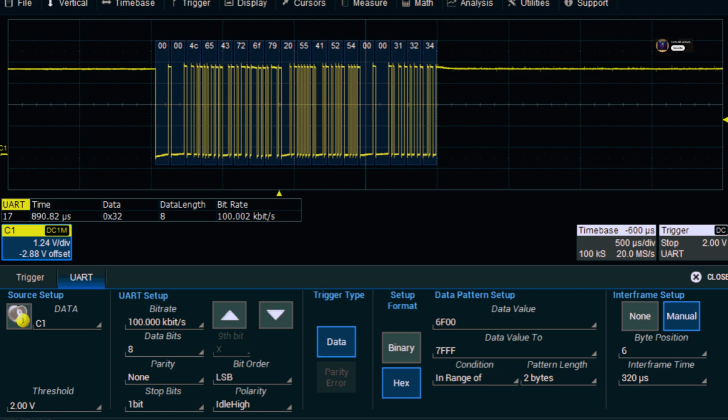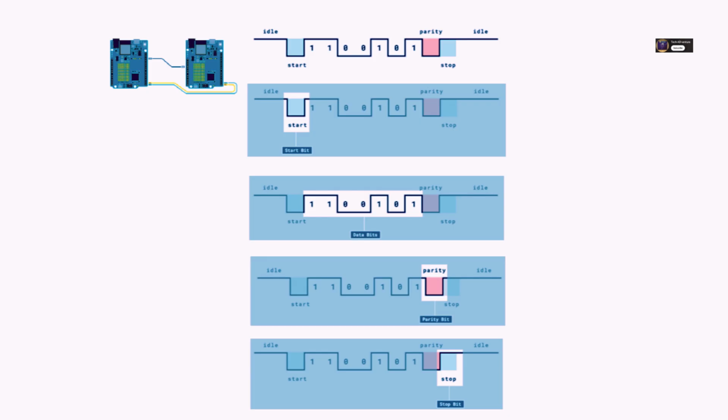You can instantly diagnose problems like incorrect baud rates, framing errors, or check if data is being sent at all. Indispensable for low-level issues. An oscilloscope can also be useful, especially for looking at signal quality, noise issues, or checking voltage levels are correct. Is it really 3.3V, or is it noisy?